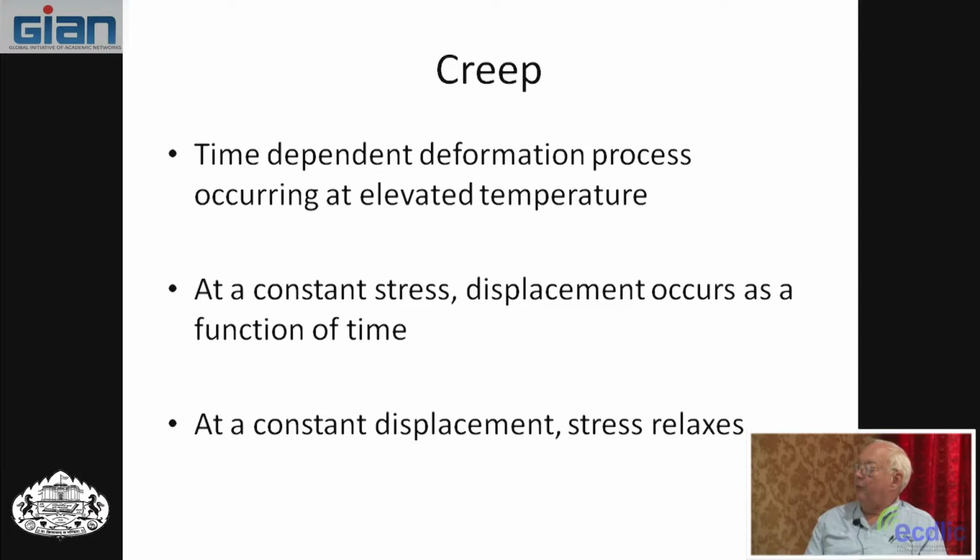Creep is said to happen at any temperature more than 50% of the melting temperature in degrees Kelvin, so absolute temperature. Now that's a general rule, but it's not necessarily true because I've seen creep at lower temperatures if you have enough time.